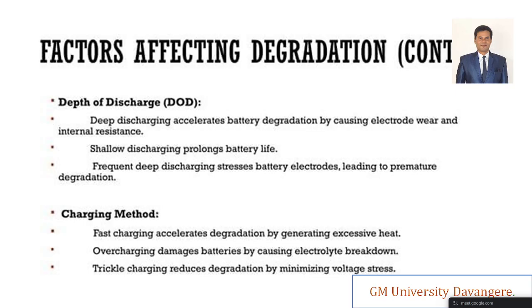Again, when you come to the concept of trickle charging, right? Trickle charging is also one of the methods, where you have low current at full charge, right? You provide low current at the fully charged state, and it will reduce the voltage stress and also the degradation of the batteries by minimizing the voltage stress. But this makes for prolonged time at 100% state of charge, and it can also degrade the lithium ion batteries.